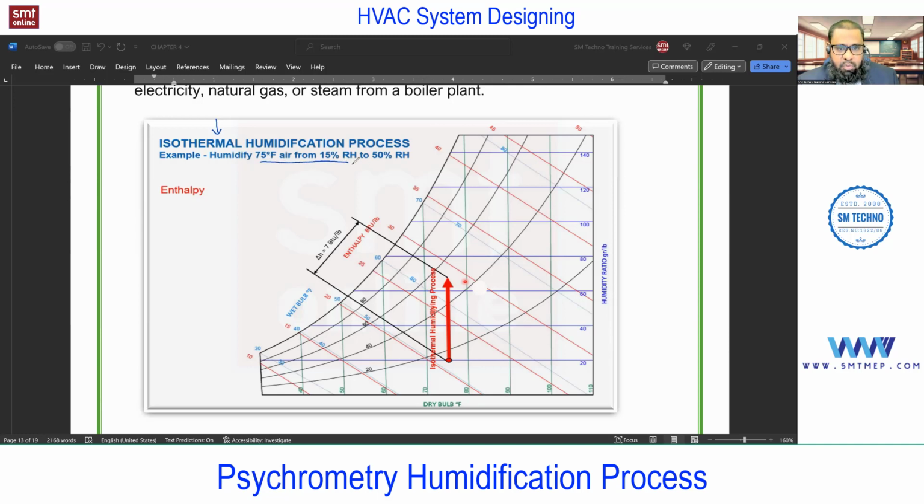We are interested in maintaining 50% RH. In this, we are not disturbing the temperature, we are just increasing the RH, as per the process. Getting the point? Temperature is constant, we are just increasing the humidity. Increasing the humidity is the process called humidification, by introducing steam.